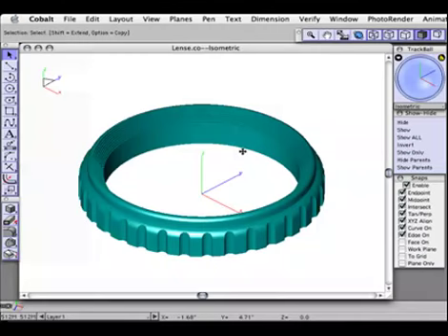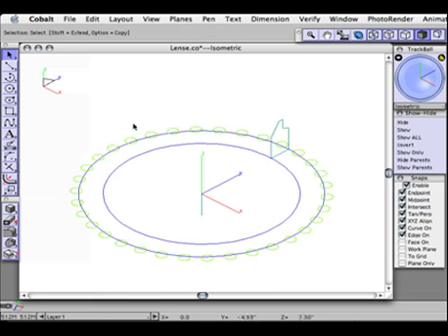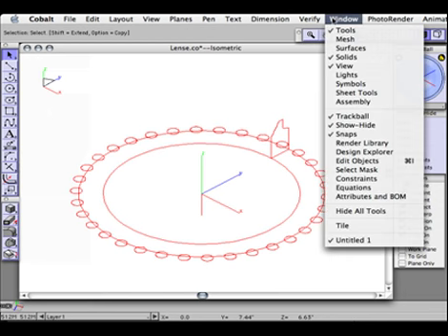In order to keep my drawing clean, I like to move geometry I'm not going to use anymore to a new layer. So I'm going to click the Show All from the Show Hide palette. Then I'm going to highlight my solid part, and then I'm going to hide it from the Show Hide palette. This shows all of my wireframe geometry I used before. Now I'm simply going to hit Apple A to do a Select All.